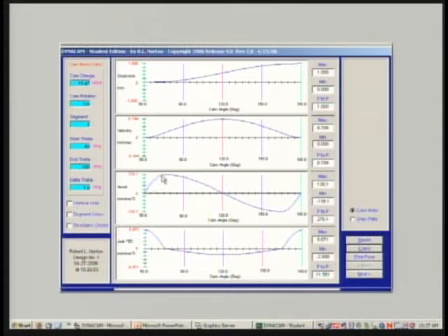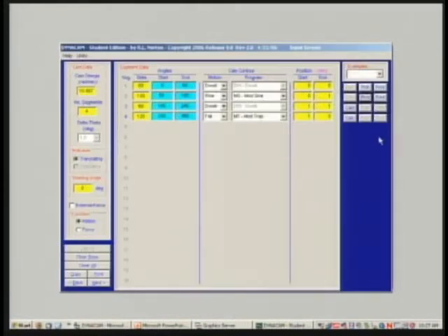It's got a rather rapidly changing quarter sine wave up to the peak at the 1/4 point there, and then a cosine down to here, and then another quarter sine to there. There's the jerk curve. Jerk is discontinuous, which is acceptable, but the acceleration is continuous, which is required. It's matching up with the dwells. We'll see that in a second when I plot all of them for you. So any one of these, once you calculate it, you can plot it.